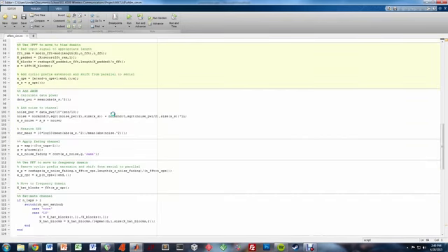Now, the IFFT, inverse fast Fourier transform, is used to move the data from the frequency domain to the time domain, and a cyclic prefix extension is added. The data is then shifted from parallel to serial. Here we corrupt the signal with noise. The noise power is calculated based off of the target channel SNR value. The fading channel taps are calculated, and the time domain OFDM signal is convolved with the impulse response of the channel.